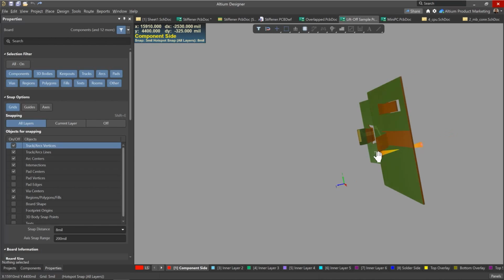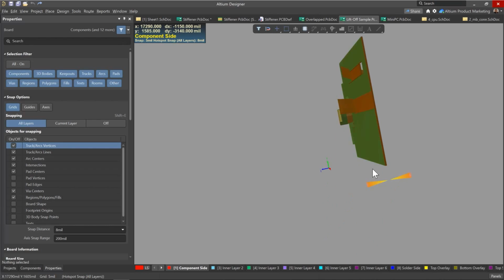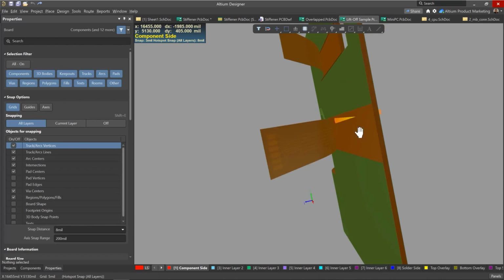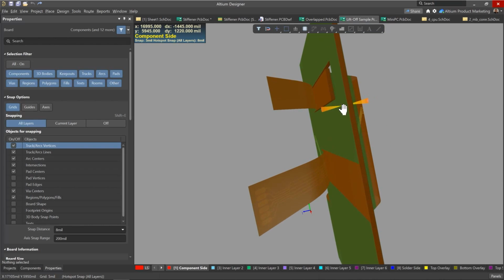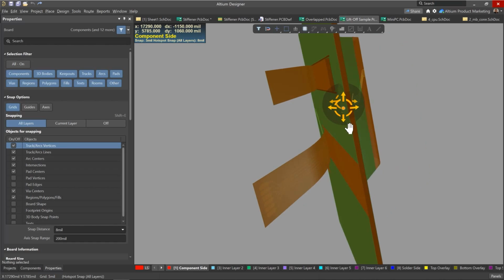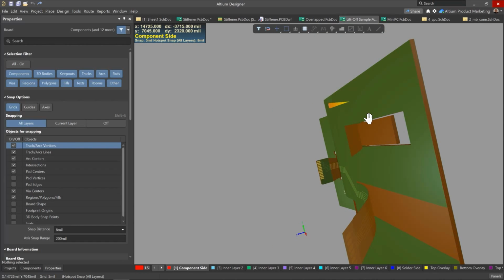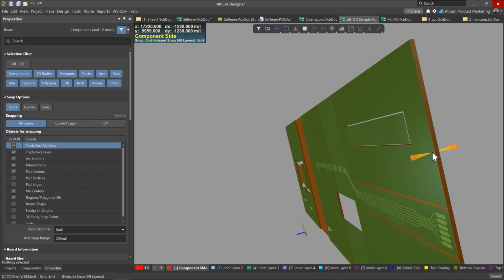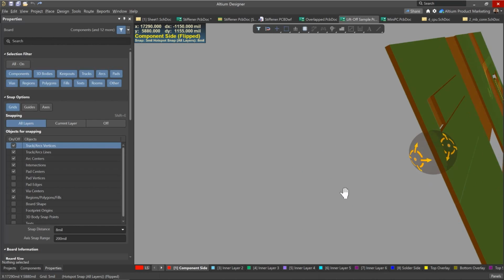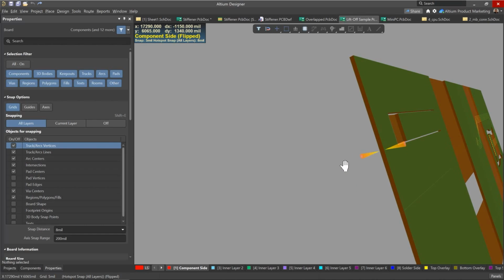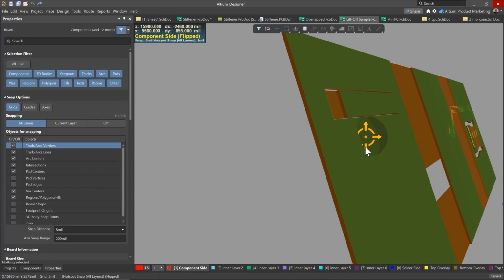we have certain materials that split up based on the stacks we've defined. And you can see in certain areas the defined rigid and the flexible area. So if I actually flatten this out again, you see this rigid and then this flat area. When I flatten it out, you're actually able to tell in the layer stack, you have the rigid area, and then you have the flexible area.